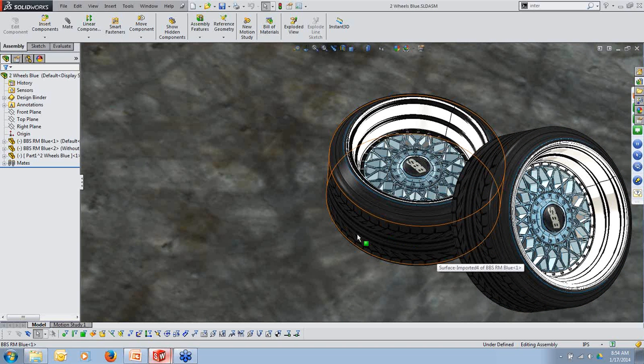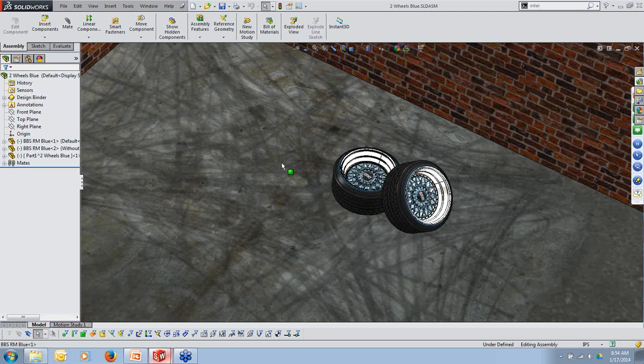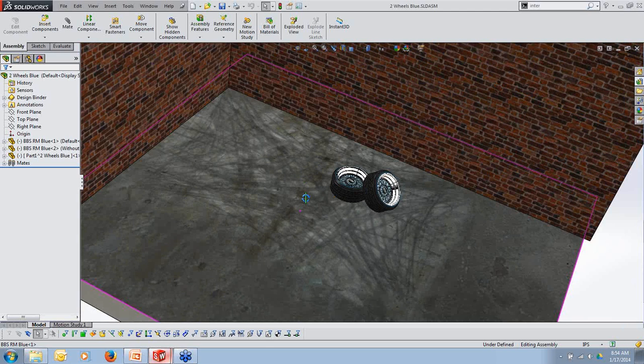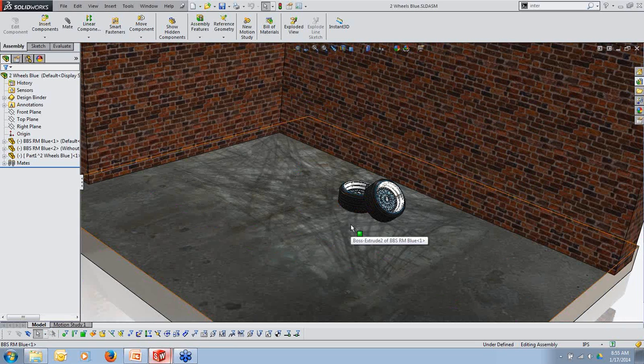Bump mapping is a great thing that you can use that will actually add detail. Just an image of tire marks, and like I said, I just built a small studio. I set up a camera that's pointed with the lens that I wanted, the direction that I wanted. You can adjust your lighting, just like you were setting up to take an image. Render is all there is to it.